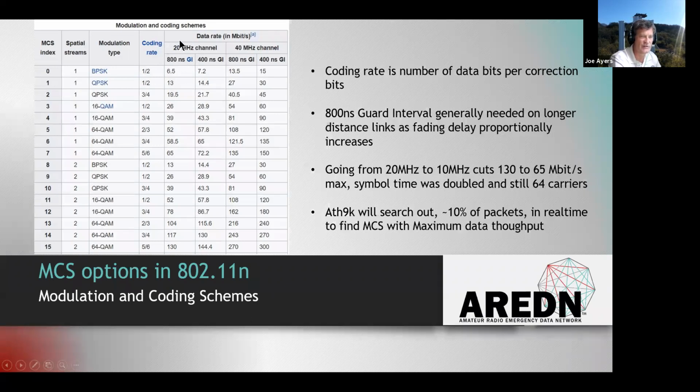And you shouldn't expect interference with two 20 megahertz signals right next to each other. They were designed that way, with all of those carrier waves, the pilots and the other carrier waves modulated in a way to minimize inter-channel interference.